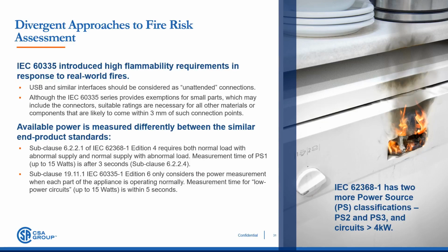In addition, within the required safeguards of IEC 62368-1 to limit ignition from high-resistance connections, there is an additional distinction in compliance requirements for circuits with power exceeding 4 kilowatts, a principle absent in IEC 60335-1. Both standards concur that 15 watts is insufficient energy to pose a fire hazard, exempting the requirements for arcing and ignition for such circuits without any additional compliance controls.